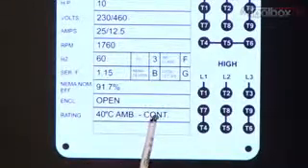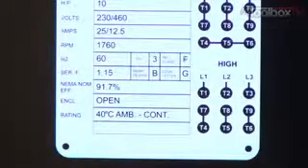It's a continuous duty motor. Continuous means that this motor is designed to be turned on and left on. It's one of those motors that you just see running all the time. It's never turned off. Maybe it's a pump or a fan or a conveyor, something like that.